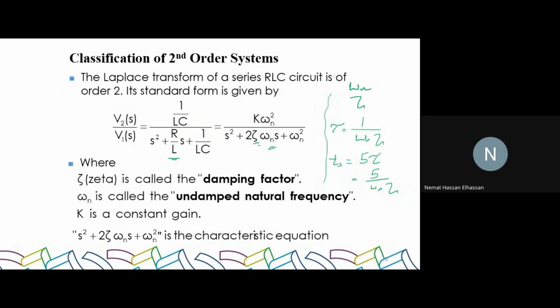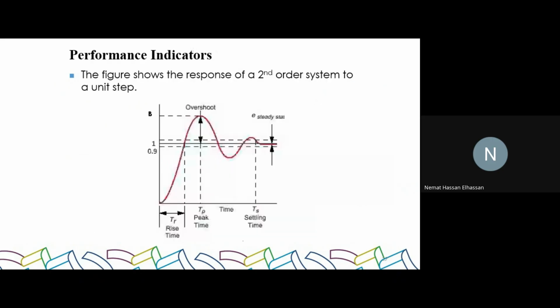Additionally, if you evaluate the unit step response, so if you have a system and you have an input and you have an output, if your input is a unit step, your output tells you a lot about the system. So sometimes you design a system and to test it, you subject it to an input that is a unit step just to see how the output will react.